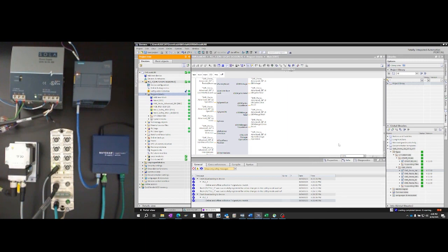Now, in order to test the SMS actuator and ensure that it's properly connected to both the process data, which is cyclically processed, and the parameter channel, which is acyclically processed through this function block, I'll add a watch table with the proper sequence.